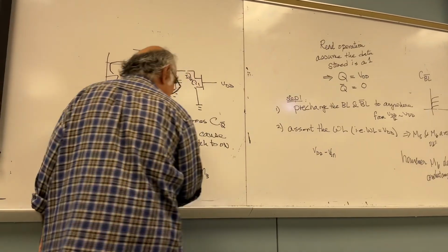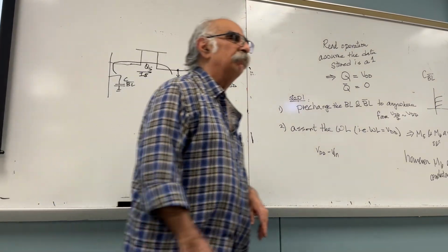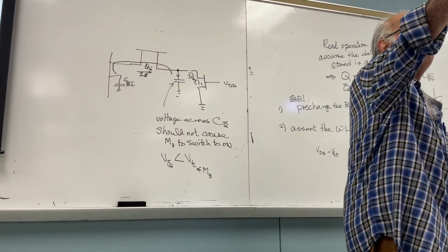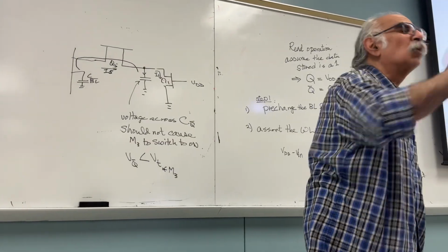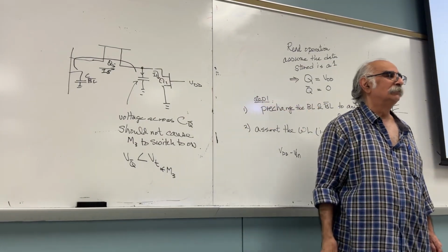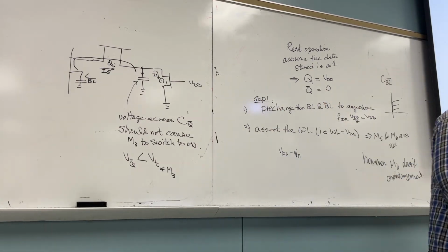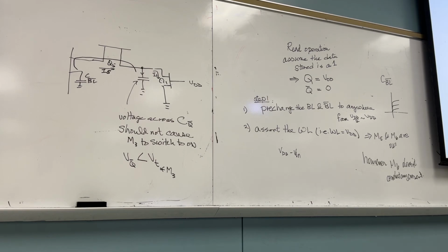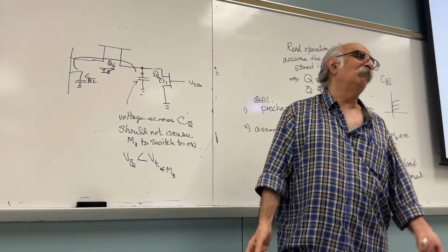As long as it does not exceed, what do I want the capacitor to do? I want it to stop what? Charging. So where is the current going to go? The I5, where is it going to go? The capacitor stops charging. At equilibrium, where is the I5 going to go? It's going to go to I1. Did you follow me or not?